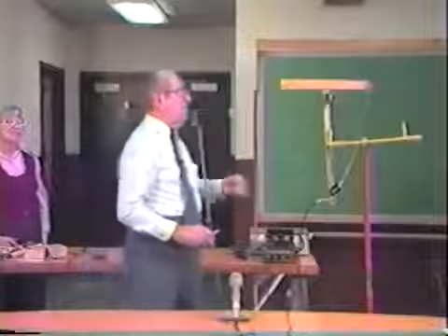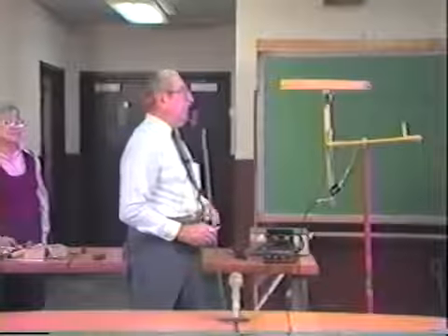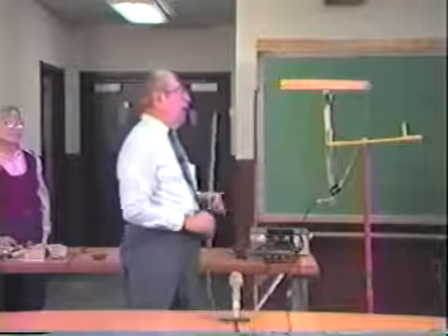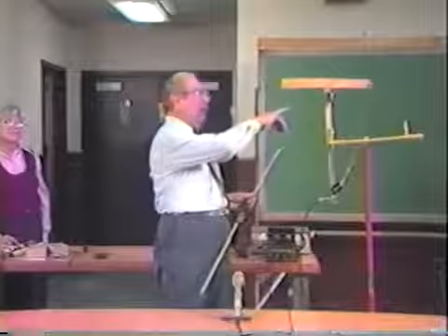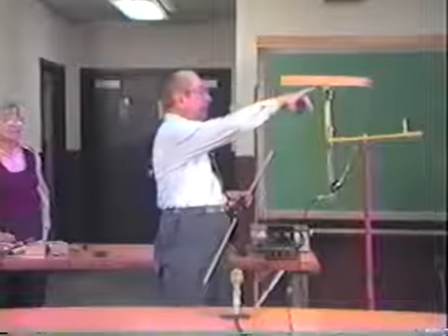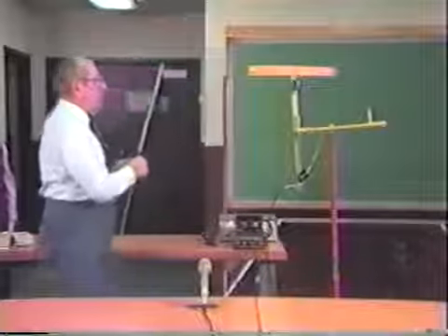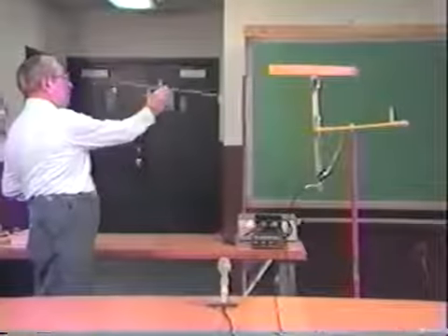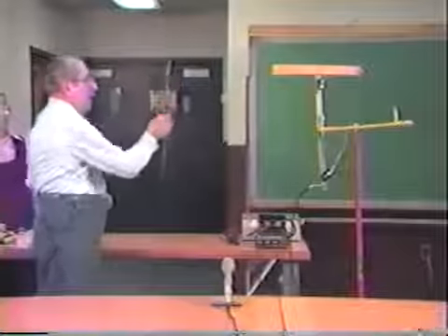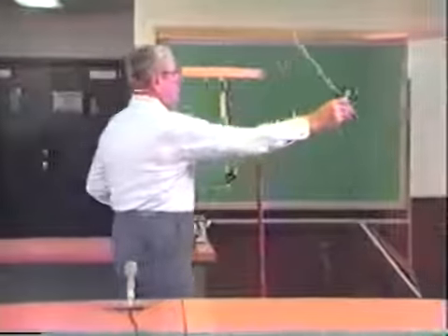The delta loop is an effective antenna. It's basically a full wave loop. And we have the same situation that we had before on the quad loop, where we have a current loop at the top and a current loop at the bottom. The antenna is basically horizontally polarized, okay, and effective, of course, on both sides.